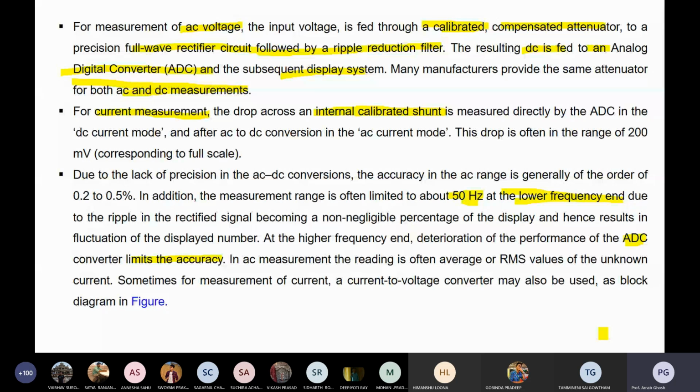When a positive pulse is coming to the switch, the switch will be shorted. When the switch is closed, the continuous signal flows through the switch. Then when that switching signal is removed, that means the PWM, pulse width modulation, off time is coming, so the switch will be off and your output will be discontinued. So the analog signal will give you zero output. Basically the switch is on, switch is off, and simultaneously that process goes on.